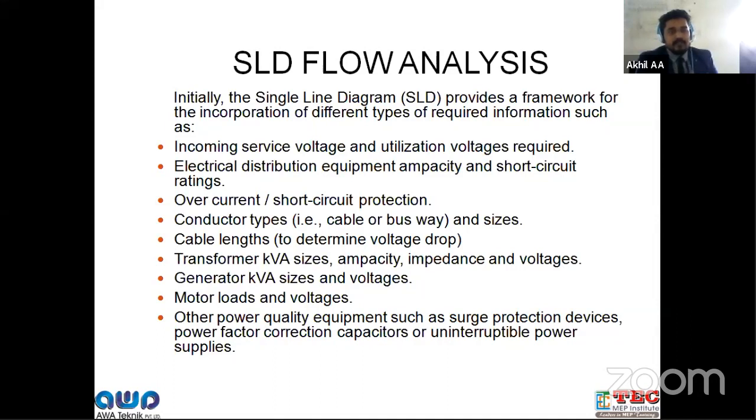So the transformer, depending on our total load or the kVA, our transformer size will be 100 or 160 kVA or above. So the incoming supply will be mentioned in the single line diagram. 11 kV by 433 volt is the distribution transformer step down voltage ratio. Okay, so you will be mentioning the voltage all over the single line diagram,